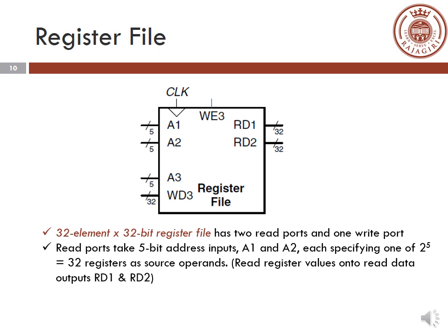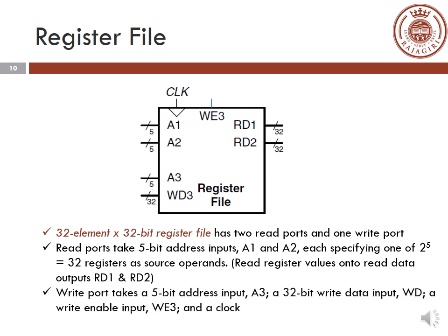Now coming on to the write operation. It's basically a memory which can be read and written, so you have a write option as well. A write operation on a register can be done by providing a 5-bit address in A3. A3 is the port associated with your write operation. In your A3 port, you will be giving a 5-bit address value, and the data to be written. Since we are doing a write operation, we have to give data as well as address.